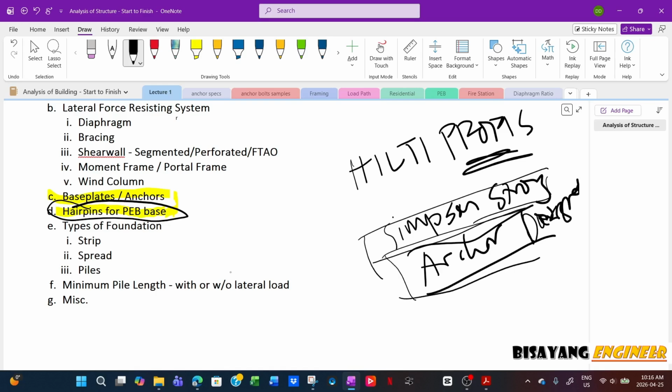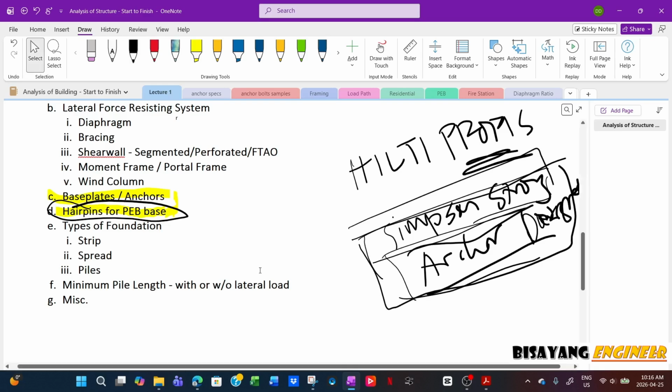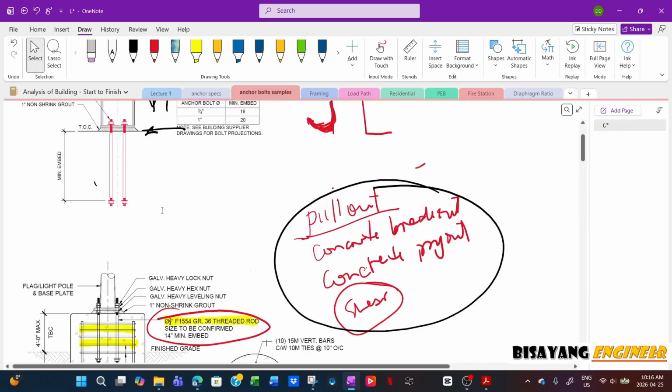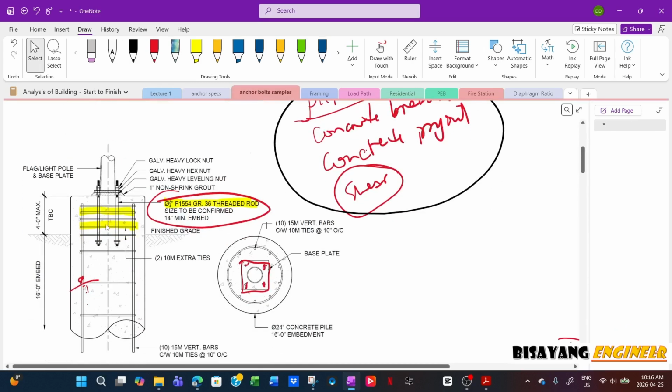So for the last five, six years, I've been using this Simpson Strong-Tie, but only if I need to check the concrete breakout, if I cannot have some kind of reinforcement. But most of the time when I do a design like this one, I will just make sure that everything is reinforced, for pull out, for shear. That's why I have extra bars to transfer that load.